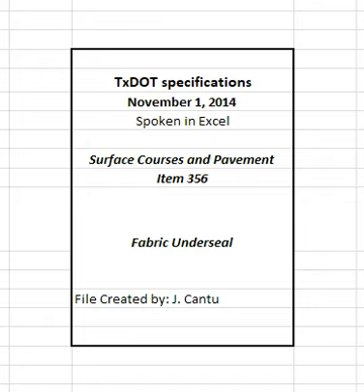4.2 Pavement joint underseal. 4.2.1 Surface preparation. Remove dirt, dust, or other debris from all joints and from the area on both sides of the joint that will be in contact with the installed underseal. Other preparation for proper adherence may be required as shown on the plans. 4.2.2 Fabric placement.